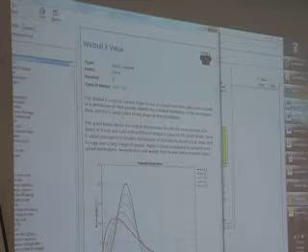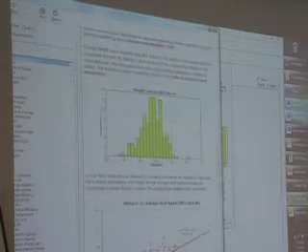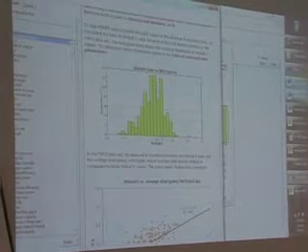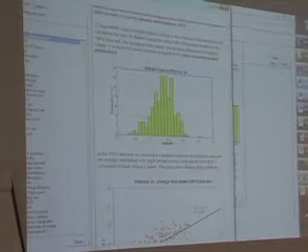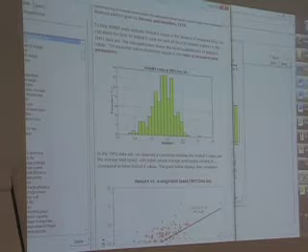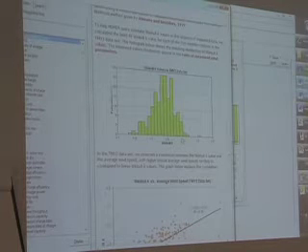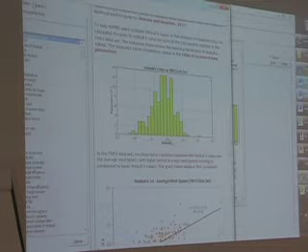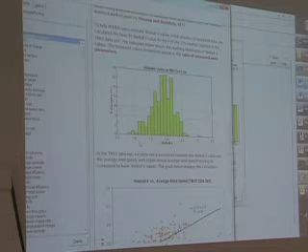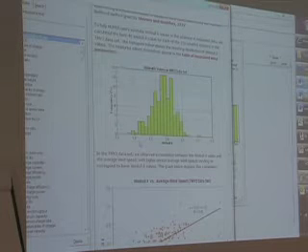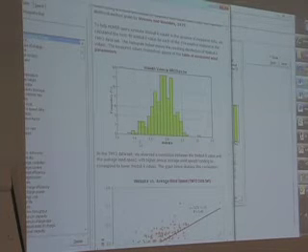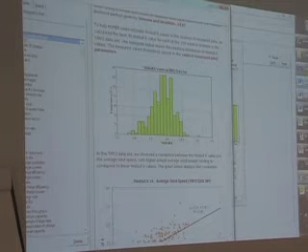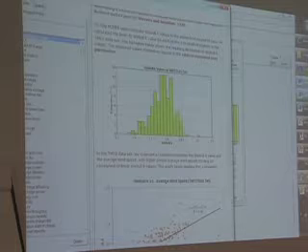So under Weibull K, we have a similar graph here. And the default is the Rayleigh distribution, which is a Weibull K of 2. And you can see, based on that database that we used, that's a pretty good estimate. If you didn't know anything, 2 is a good estimate. If you happen to know the winds are fluky, you might pick a slightly smaller number. If you think they're steadier than average, you might pick a slightly higher number.